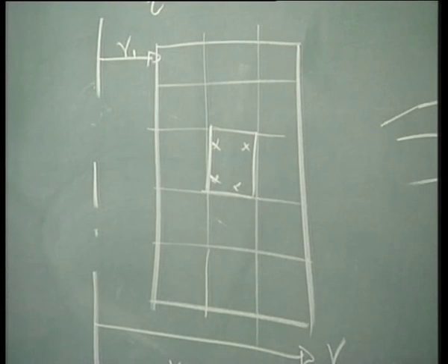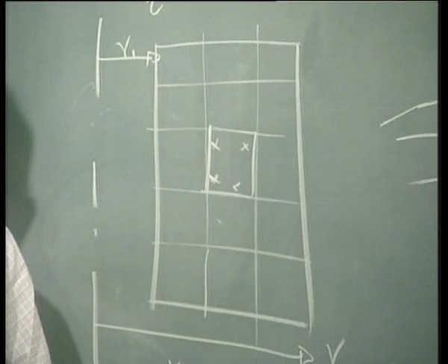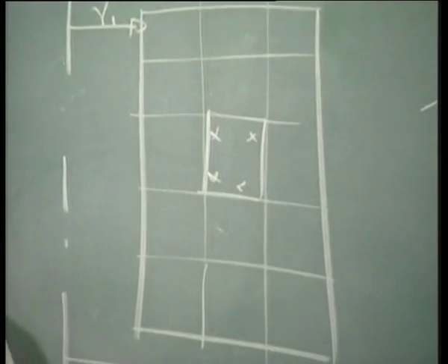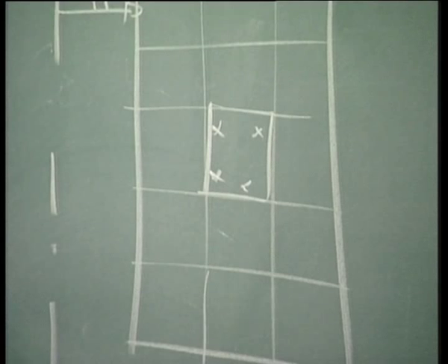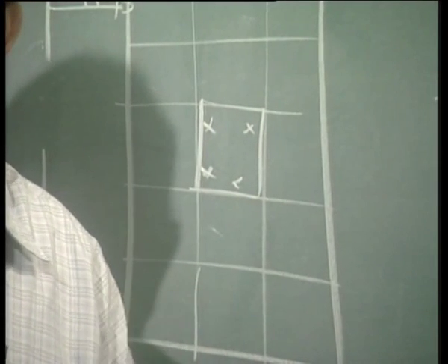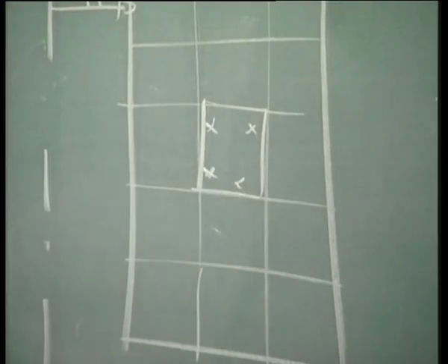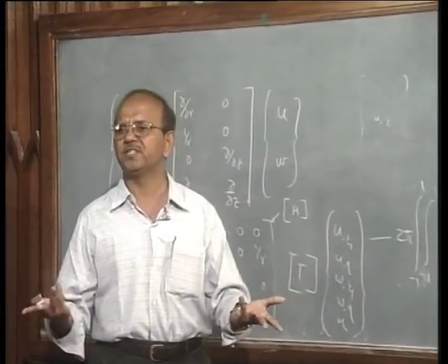Now how do I get the radius at the Gauss point? The rule is very simple, because I am using an isoparametric element and the shape of the element is interpolated with respect to the nodes, or in other words the coordinates are interpolated from the nodal values through the shape functions defined in terms of psi and eta. So the problem becomes very simple.